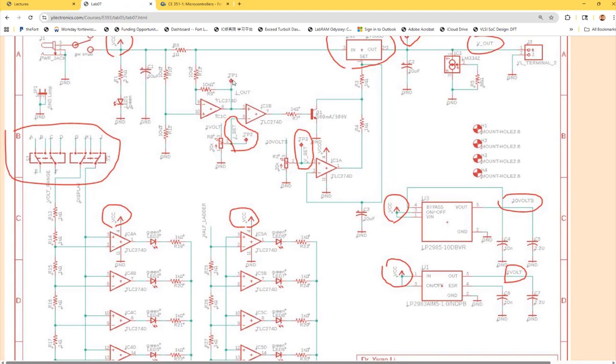And also for the testing point, it's really beneficial to have a testing point like this. If you go to the PCB of this schematic, these testing points are just the through holes, right? So it allows you to push your probe against that little metal piece, the through hole, so you can probe it as a testing point. So this is something you can use for your schematic. When you're designing a circuit, you want to have some of the voltage nodes available to be probed, so you can set a through hole over there so you can probe it.